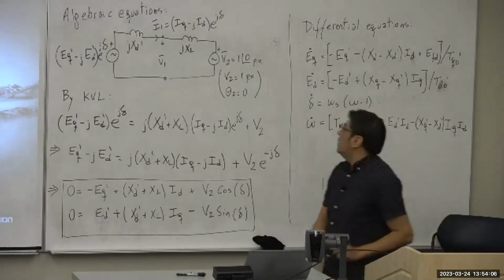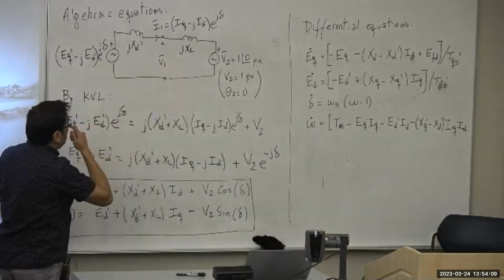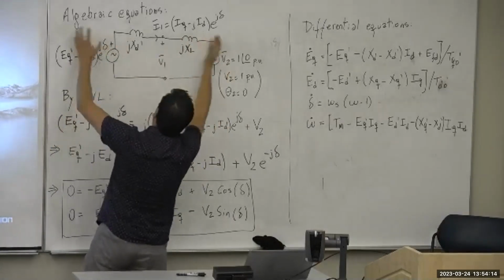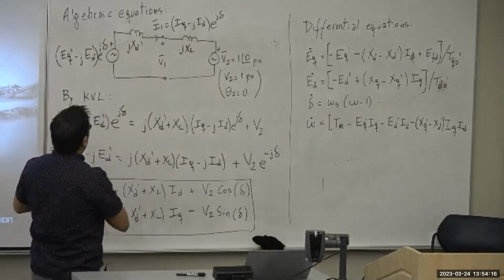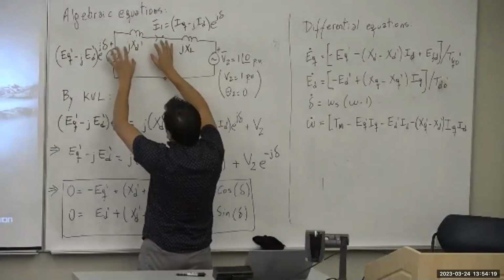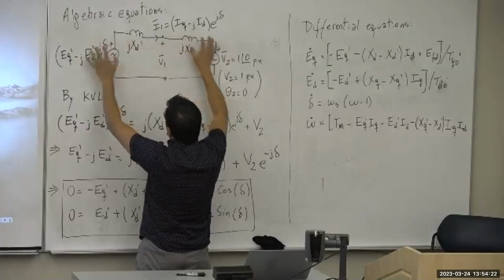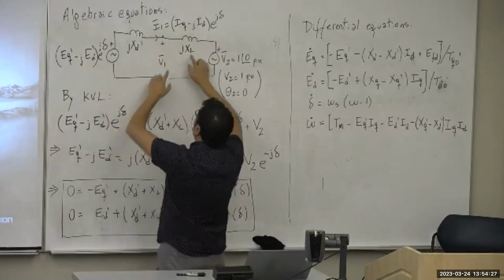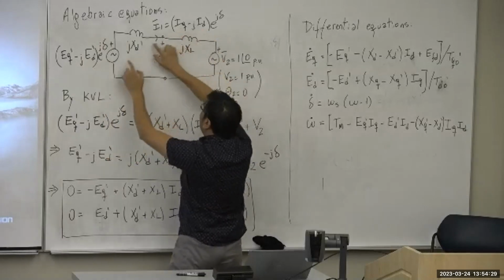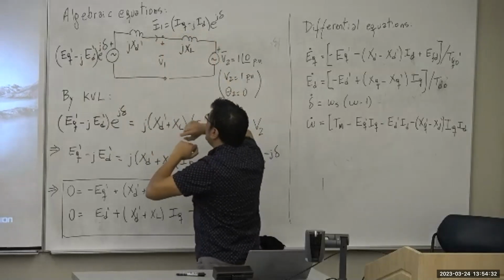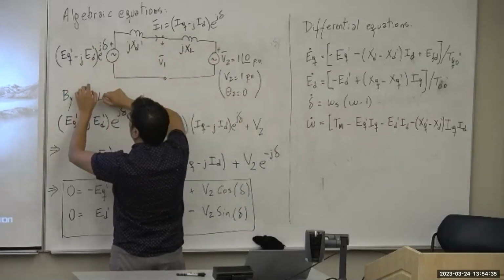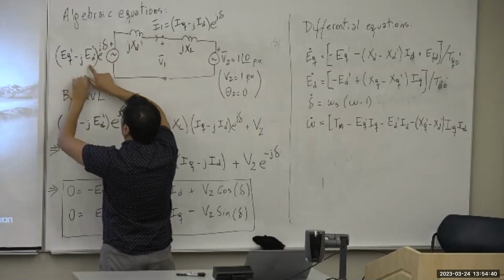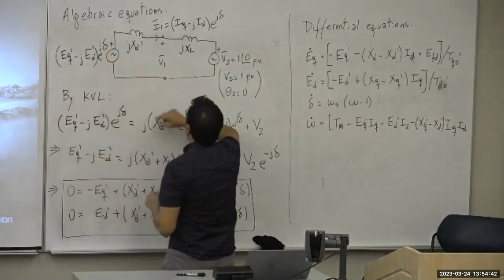So here we have the model of the machine, and this is for dynamic simulation. When we clear the fault, then this is what we have to consider for the machine. And this will be related to the algebraic representation of the machine that will connect the algebraic variables, which in this case are the current in the stator in the machine, with the state variables in the machine. The state variables in this model are the voltages EQ prime, ED prime, and the angle delta.